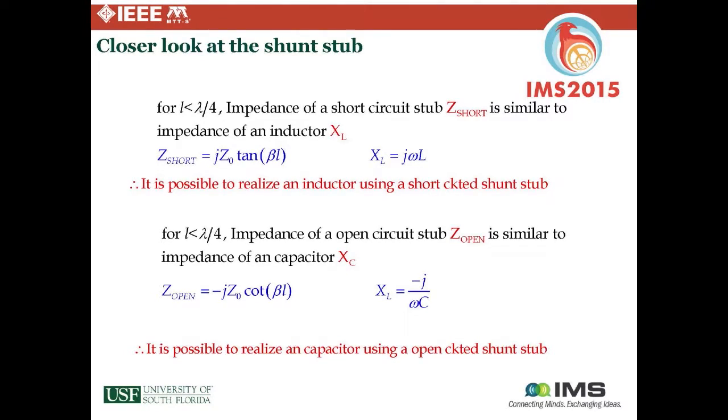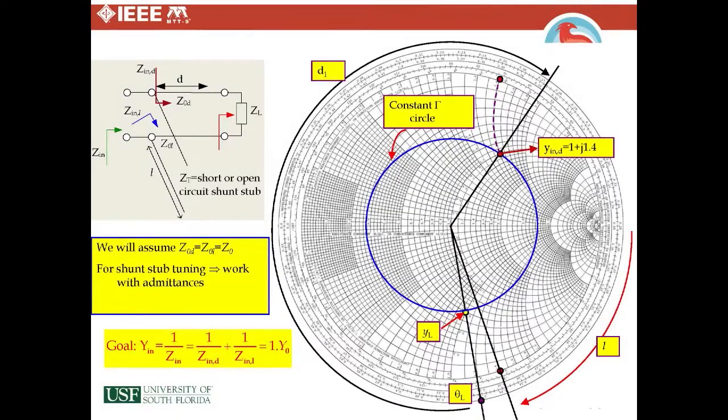It doesn't have to be for the theory, but it does have to be for the statements that I made, for it to behave capacitively. What happens on the Smith chart is that the position of an open circuit is over here on the right. If you rotate that a quarter of a wave, you rotate along the outside of the Smith chart. A quarter wave brings you all the way over here to a short, which is all the capacitive side of the Smith chart.